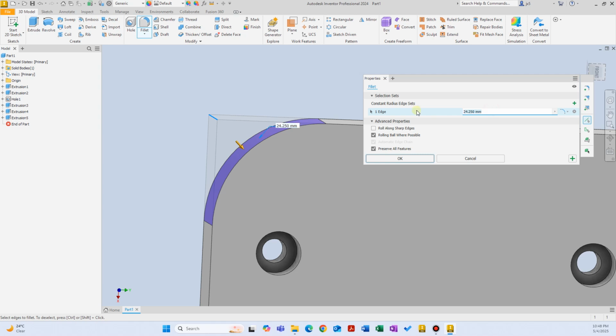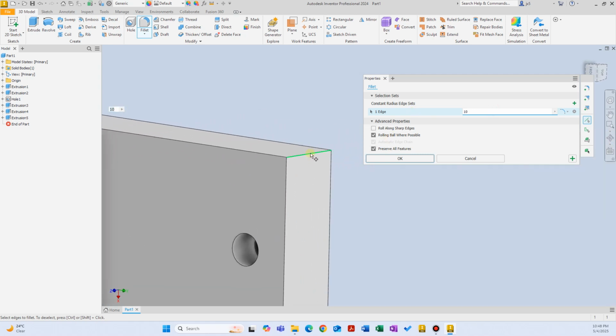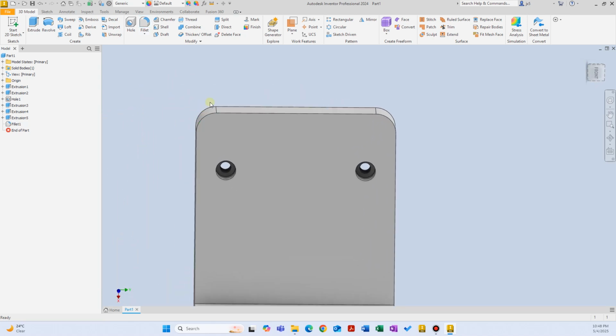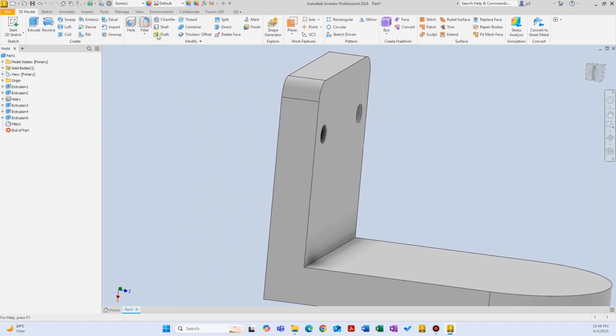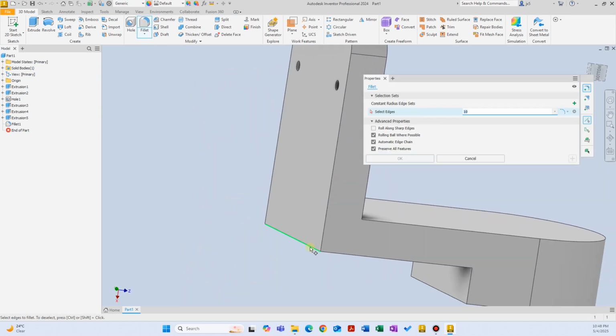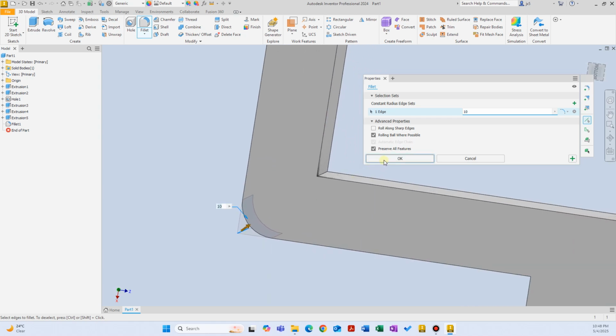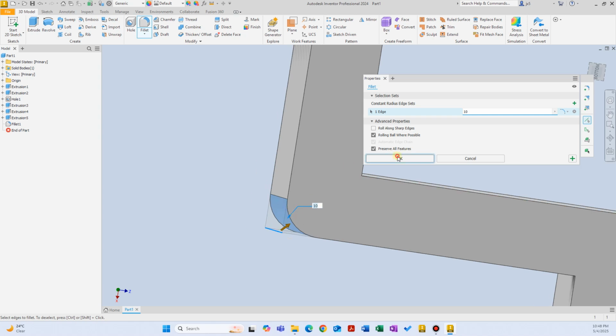Let's enter a value here and let's call it 10 millimeters. Let's say it's a 10 mm fillet. And let's just add 10 more millimeters right here. So now we took material out from those corners. And again, you can do the same thing here, right? We can just select this edge, for example. Again, that is taking material out, and that's just adding another fillet to that corner.